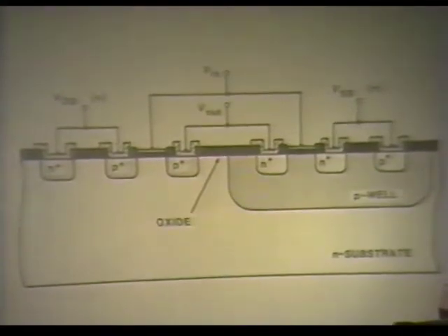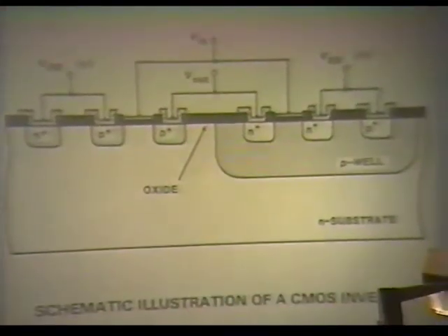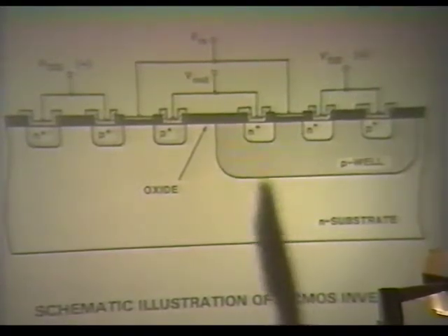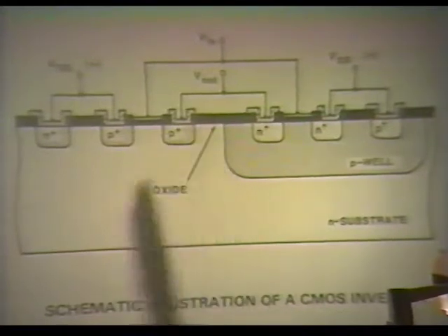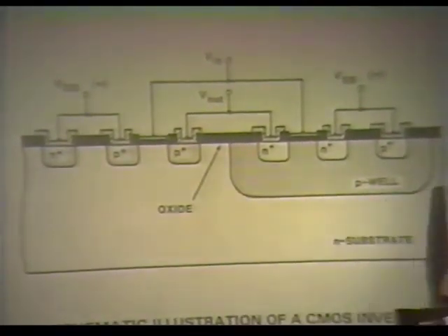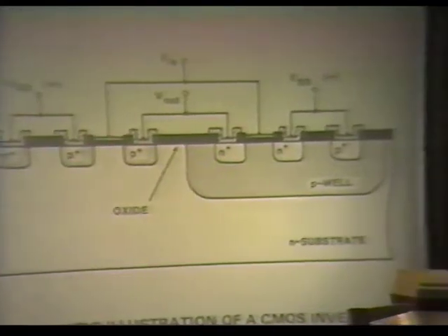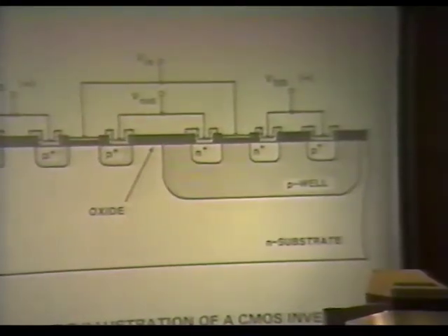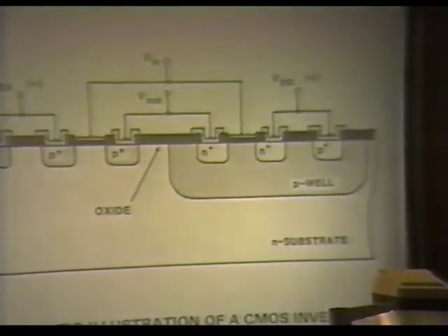Now, say something about DI. Okay. Now, DI will prevent that, because if you build a DI circuit, you will put this P-well in what we call a tub. DI stands for dielectric. You will build an oxide there, which is a dielectric.